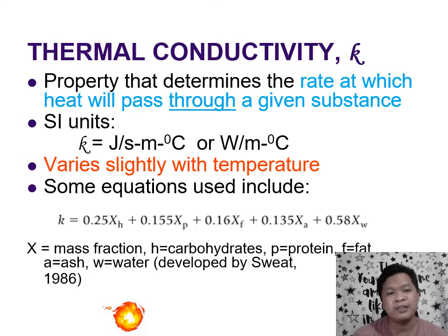No? So for the same stove setting, the same amount of food in the pan, if your pan is the same substance but is thicker, then it will take longer for the food there to cook. Similarly, you're less likely to burn your food because the rate of heat transfer is lower. So the higher the thermal conductivity is, the faster the heat transfer will occur.